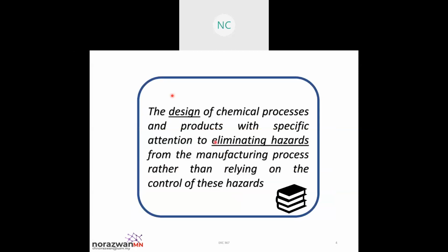So the definition of ISD is the design of chemical processes and products with specific attention to eliminating hazards. You try to eliminate hazards from the manufacturing process rather than relying on the control of these hazards.